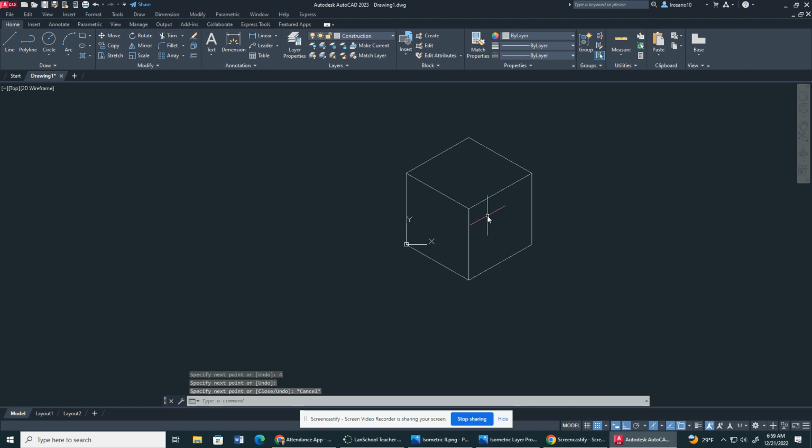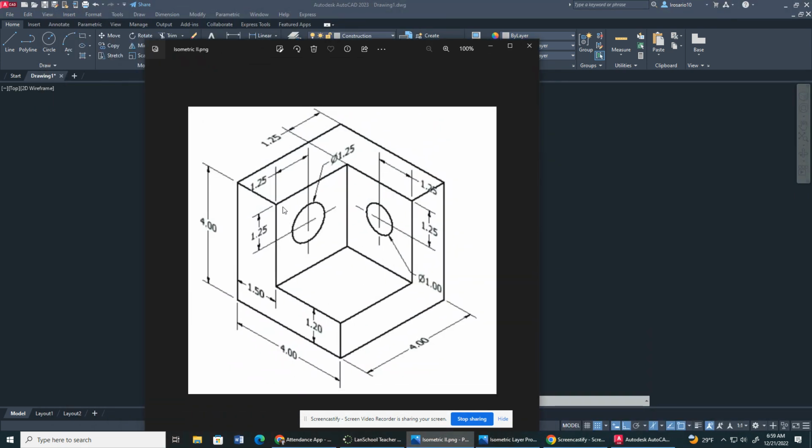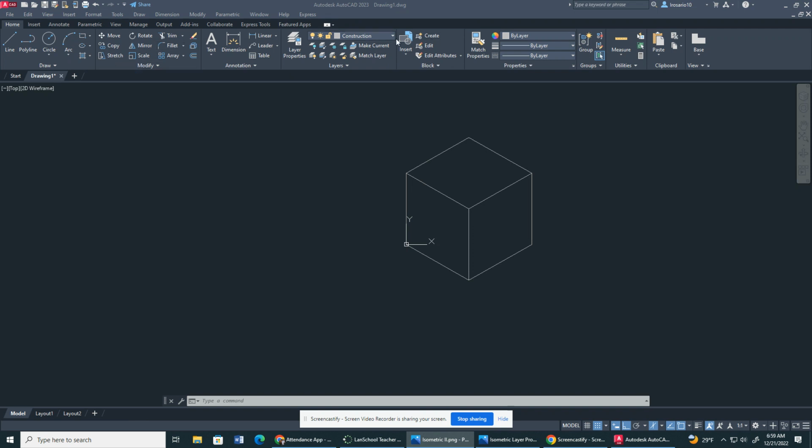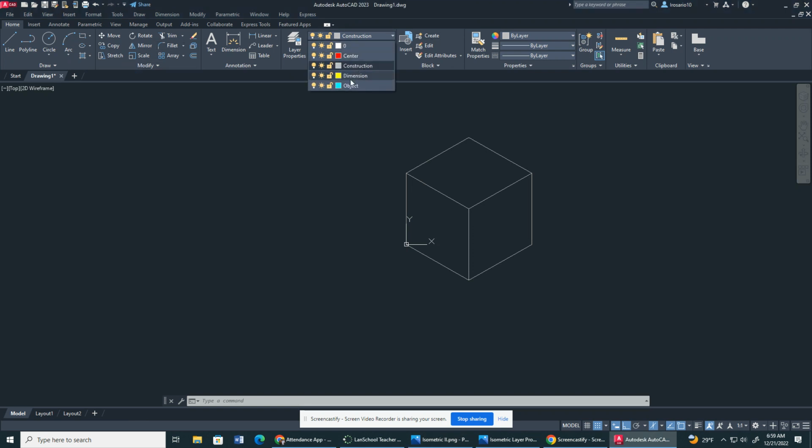Now, we are able to start drawing the finer details, as I like to call it. So to begin, I'm going to go to Object, Layer Property. I'm going to change my view to Front View. I'm going to go to Line. So I start in this corner right here. I go down. I go up this way. Now, I have to go up 1.2 inches.